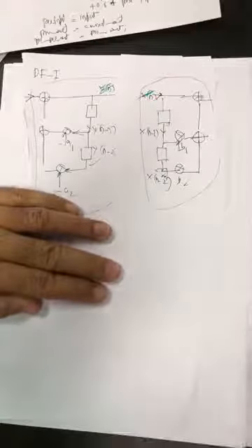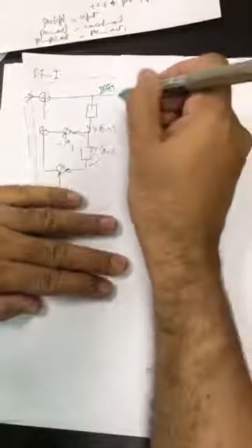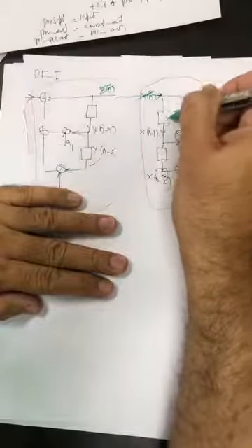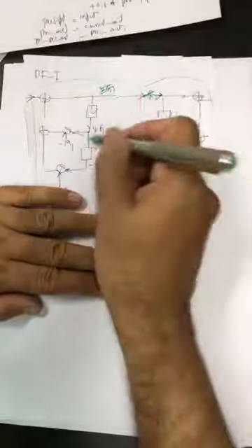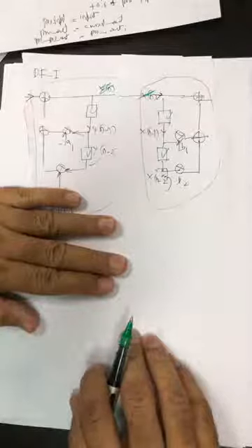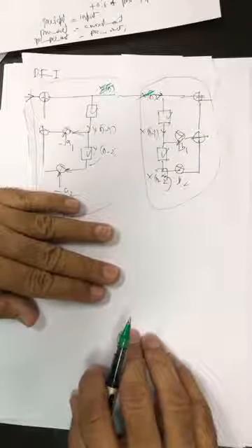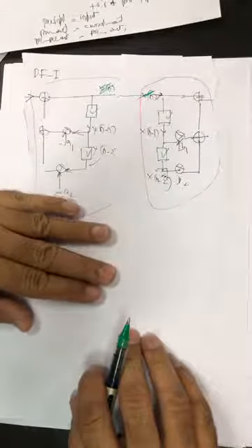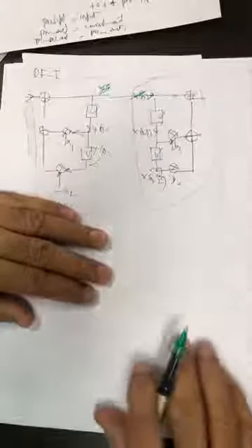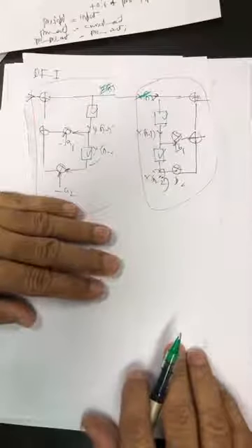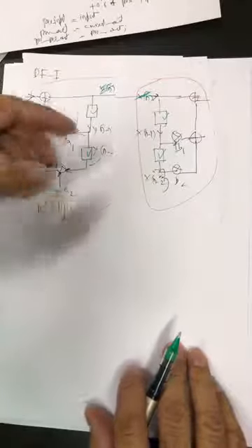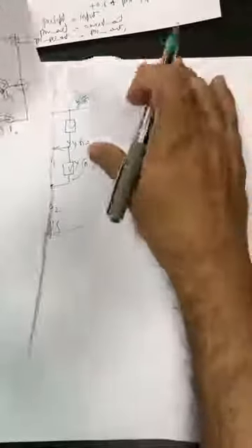Interesting. If you do this, then you find out that it is the same value which you are storing in this register and this register. So you can reduce the number of registers, the number of storage elements. And this is what takes the power and the area, because registers take power once at every clock. So this was the first approach of